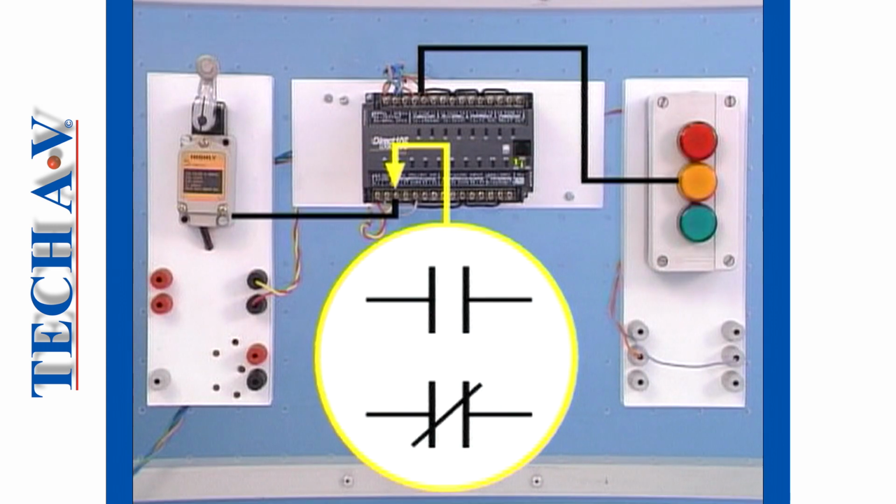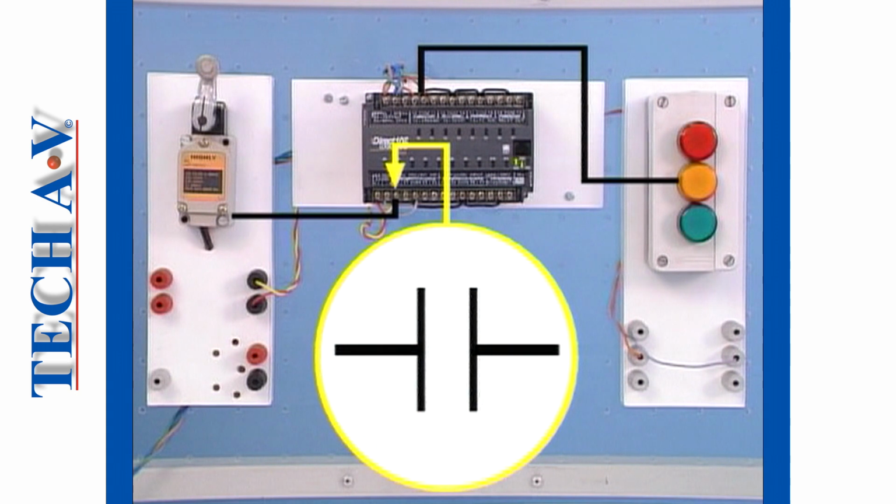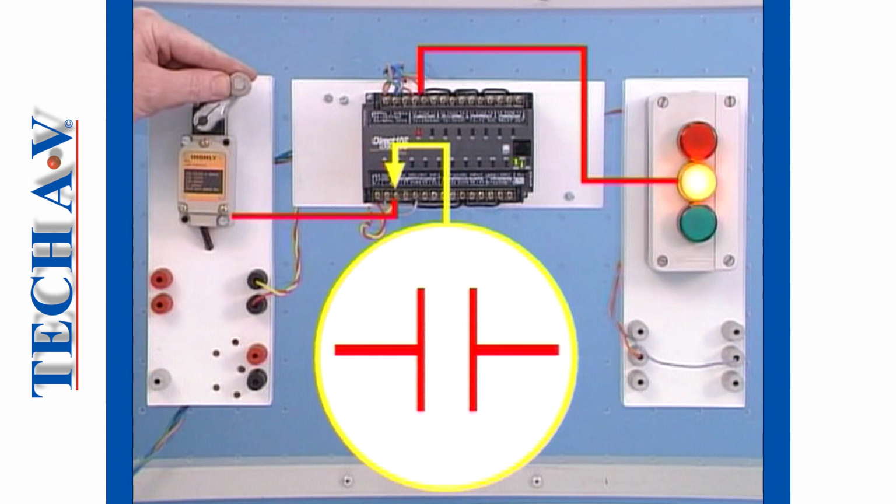When we replace the relay with our PLC, we see that the imaginary PLC relay responds in exactly the same way as the real relay. Now, this is what happens inside the virtual world of the PLC when we select a normally open contact in the logic. Initially, when the external device is not sending a signal to the input of the PLC, the output point is off. But as soon as we send an on voltage signal to the input, the output turns on.